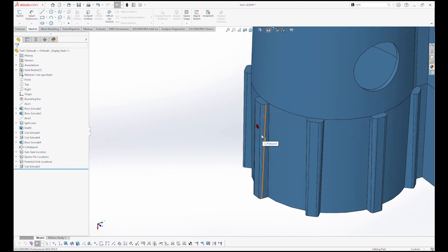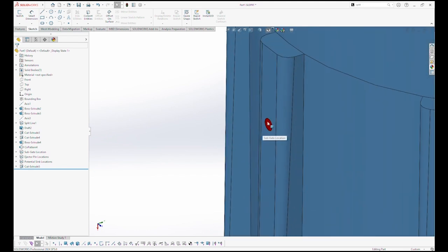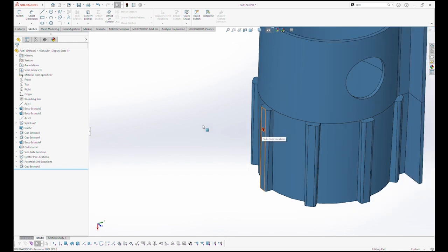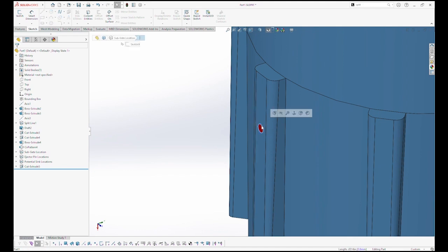Basically your gate diameter, if you wanted to sketch that in for yourself on a part, we have a DFM team that will review this, and there's a lot of different factors on how and why this changes. But if you want to know what this diameter is, a rough rule of thumb would be the diameter of that gate should be at least half of the thickness of the part. So in this particular instance, I believe that's what we have on that part.